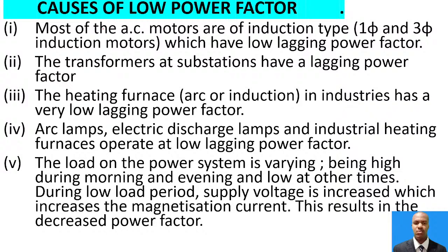And during the low load periods, the supply voltage is increased, and this increases the magnetization current, and this magnetization current results in decreased power factor.